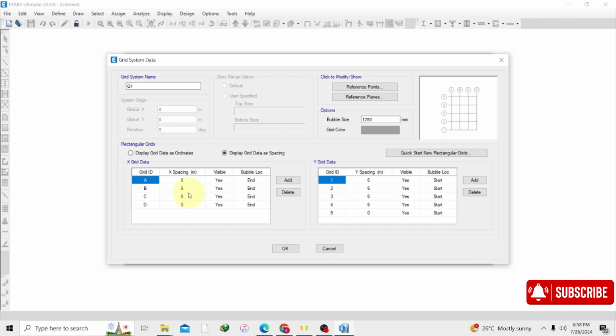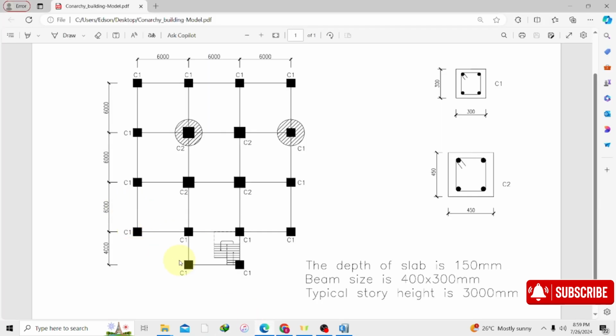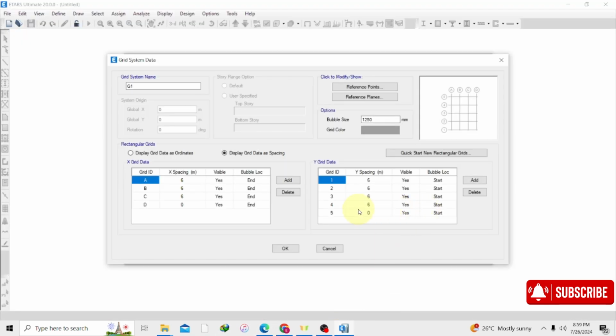So we are not going to change anything here in the x direction, but we need to change our last value. That's the 4,000 mm. You have to change it here. So our 4,000 is going to be somewhere around here. So we have to edit these grid lines. We have to notice that whatever you change here, it replicates here. So we are going to just minimize this dimension to 4,000. With grid lines, we have grid line 1 and grid line 2. So 1 and 2, where do we have 1 and 2? This 1 and 2. So this is the spacing we are going to change.